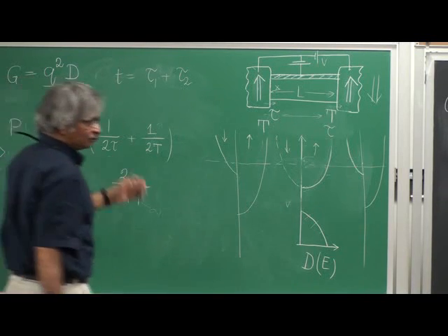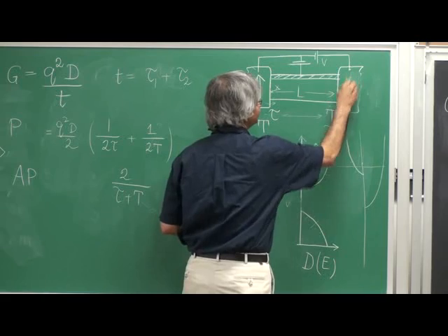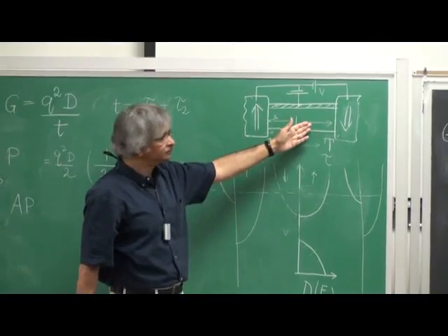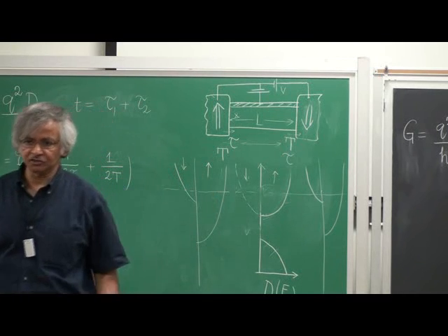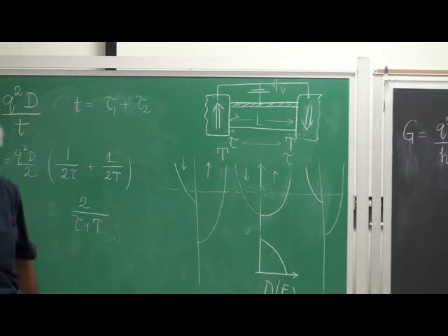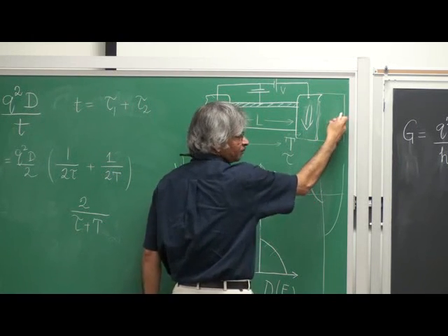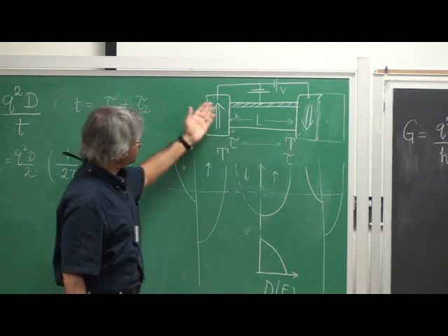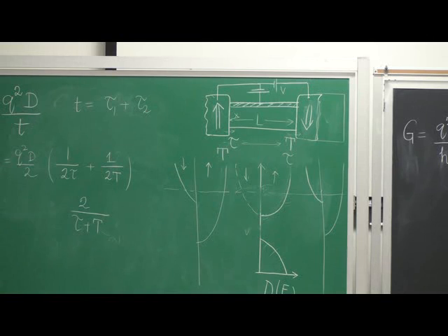But what people found was that if you, let's say, it looks like this, so it's anti-parallel, and you run a current, if this magnet is thin enough, thin meaning like 2 nanometers or so, not a big thick magnet, so it's like a thin magnet and the real contact comes after. So this is just a non-magnetic thing, but you have a little thin monolayer there. Then what they found is when they run a current, with enough current you can actually turn it. That's the spin torque effect. And that's why this again I consider is a major advance here.